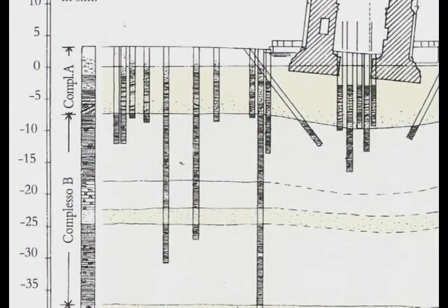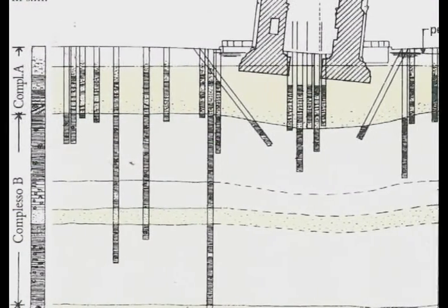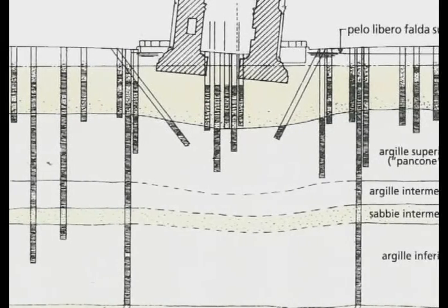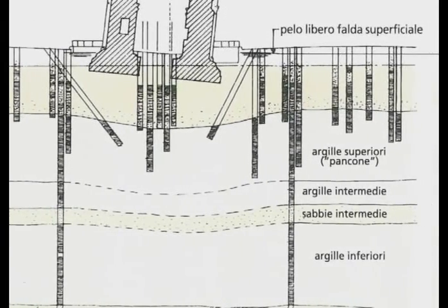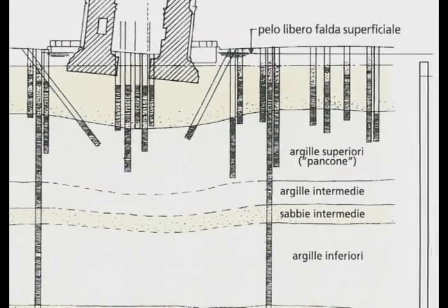And the other thing we did was we found that each year the water table would go up and down due to very heavy rains in the autumn. And that rising water table always gave the foundation of the tower a little bit of a shove by its buoyancy effect. And we've stabilised the water table, and that effect has now stopped. So we reduced the inclination by this very simple way of soil extraction, and we stabilised this very important effect, the water pressures, the water table.